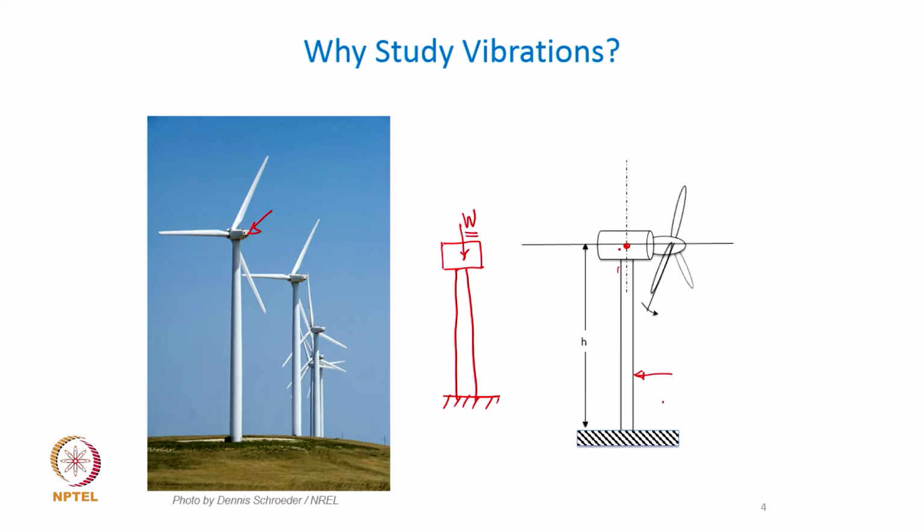Now, presuming again that the designers have taken some care that the center of mass of this entire system is coaxial with the column, the simplest way to size the column is to use our basic relation between the stress induced from the load which is acting on the column or on this structure based on the cross sectional dimensions. And if we assume it to be a solid circular structure, then this is the way we would go about finding out the stress in this column.